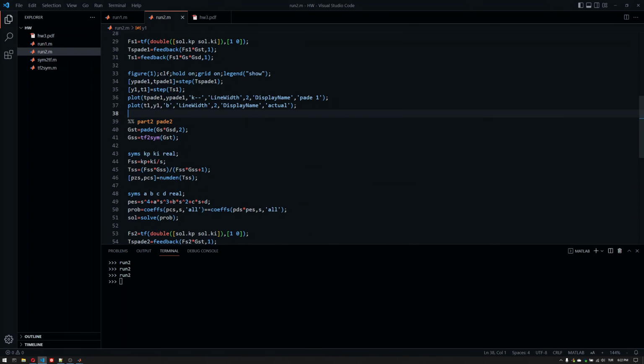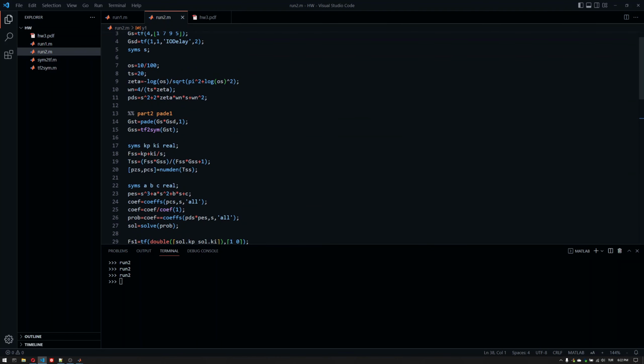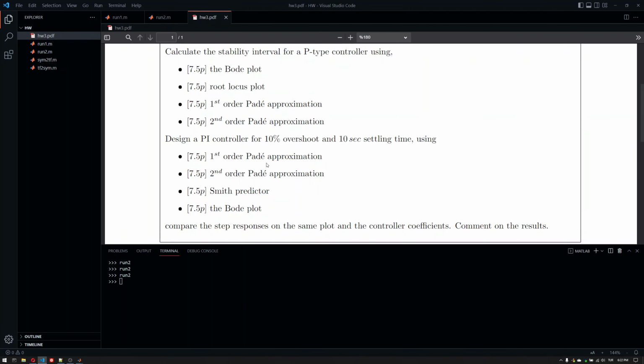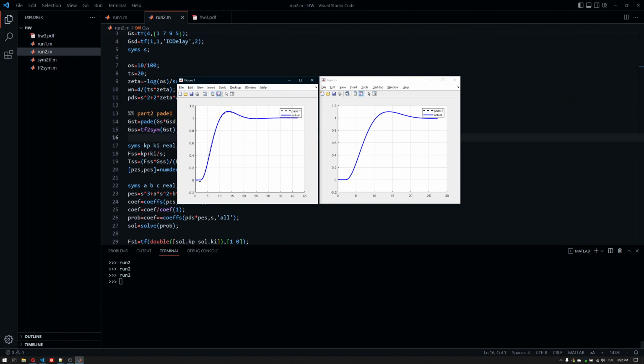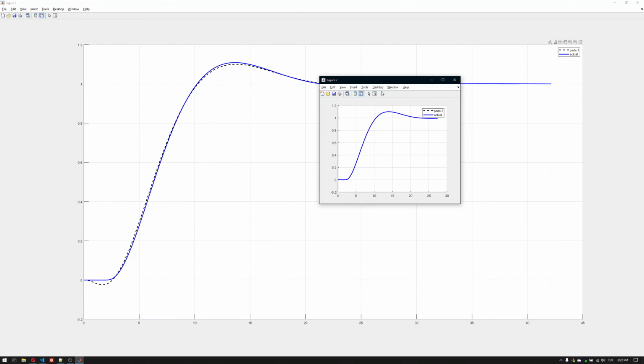This is just for you to solve the Padé approximation and design a controller for that. But actually, if we had the ability to design something, we would transition to PID. But here we have a comparative study, therefore everything is about the PI controller. Ideally, this would have been a question with a PID controller. But yeah, this is the solution. If we take 20, it works like a charm. If it's 10, it doesn't. But we didn't do anything, so it's also not really that important if it's 10 seconds or 20 seconds.